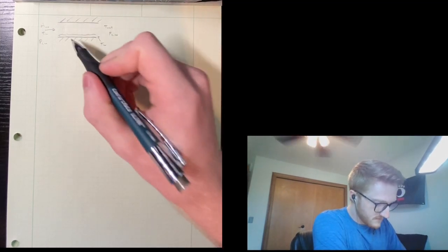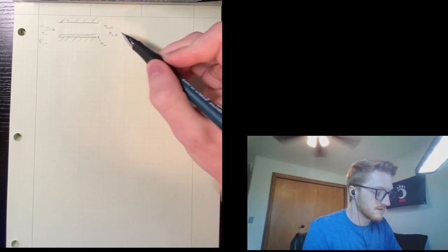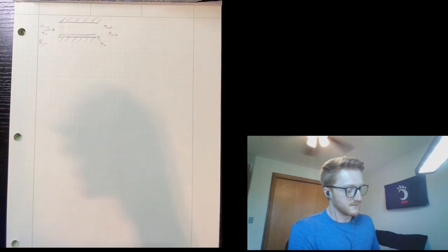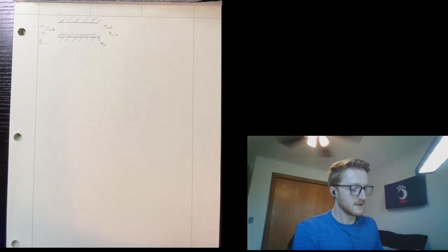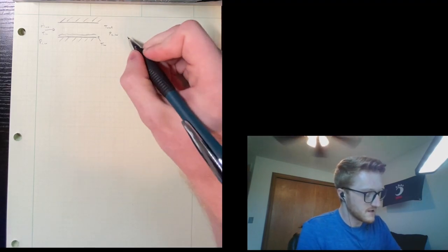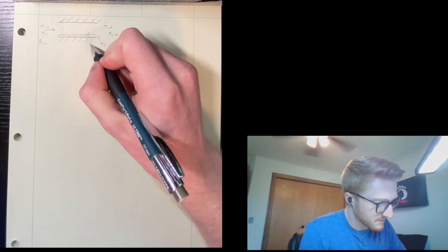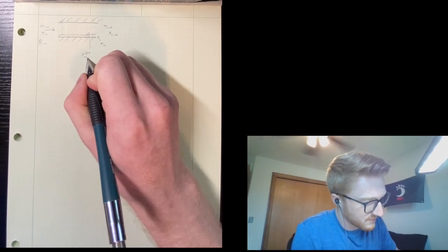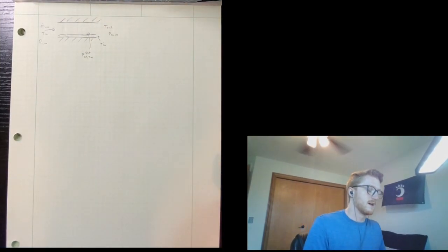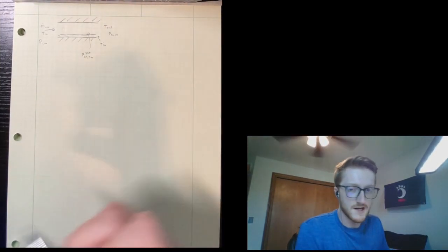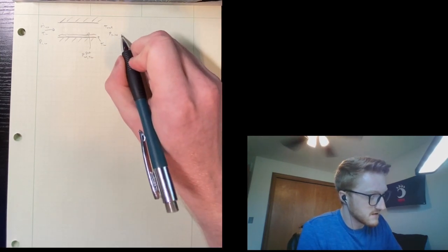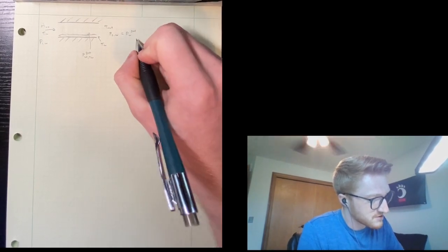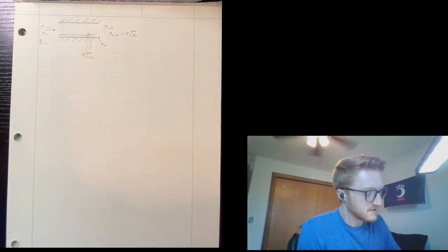And so you're going to have an outlet temperature of the air with a partial pressure of the water as well. As this air flows across, it's going to become saturated. At the surface of the water, you're going to have a partial pressure that is saturated with water at TW. Since the pipe is of infinite length and the air is allowed to saturate, the partial pressure of water in the outlet stream is equal to the saturation partial pressure of water at TW.